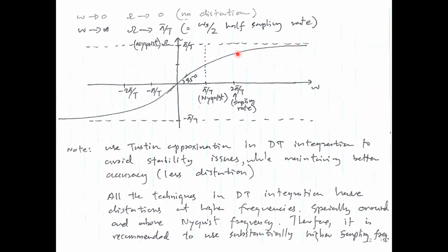And if you come closer to the origin, somewhere over here, you will see this is 45 degrees. There's some linear region here. This is the perfect mapping between omega and capital omega, right? All of these low frequencies that go into the numerical integrator, Tustin, Tustin also accepts as they are without any warping, as long as they are very small in this area.